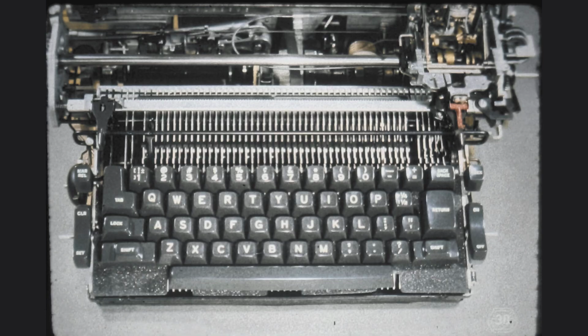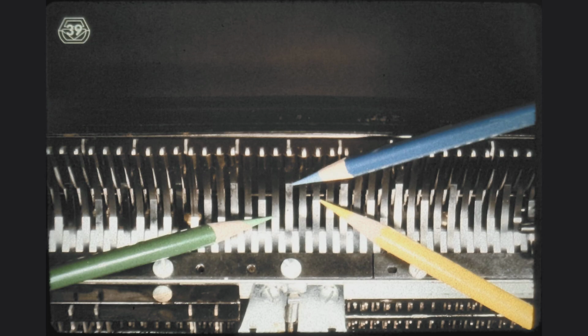As we mentioned earlier, one of the most critical factors affecting the success of the serviceman is satisfying the operator when it comes to the touch of the keyboard. To equalize the amount of finger pressure the operator has to produce to depress keylevers of different rows, IBM has provided auxiliary keylever restoring springs, which are simply placed under the regular keylever restoring springs.